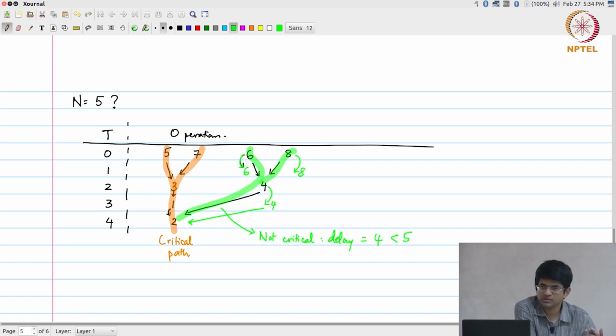Still not going to work, because I have two multipliers sitting at time instant 0 on my critical path. They can't be moved. In my original schedule, the one that is written in black, 5, 7, 6 and 8, all the multipliers are scheduled at time 0. The only way I can do that is use 4 separate multipliers. So as things stand right now, with my original schedule, 5, 6, 7, 8 are all scheduled at time 0, I need 4 multipliers.